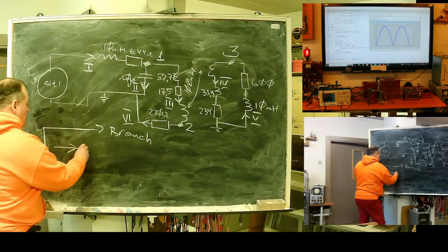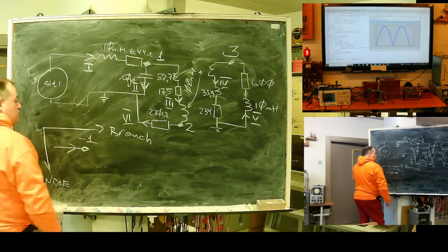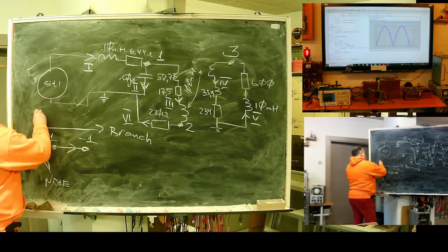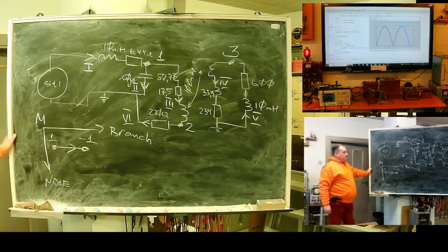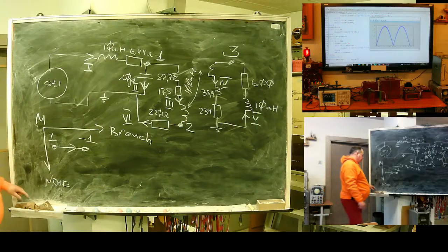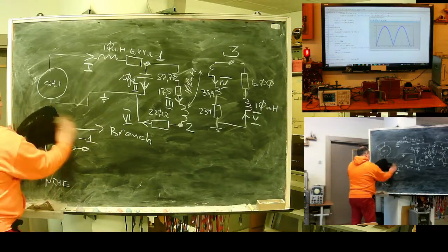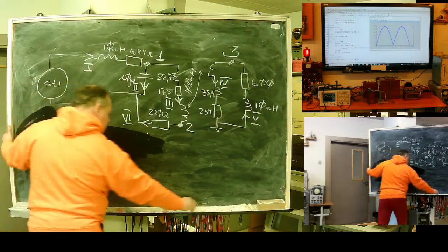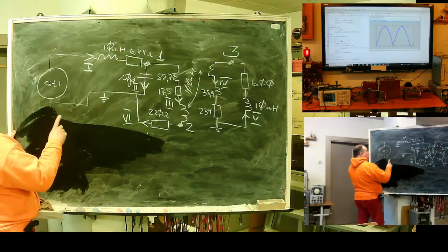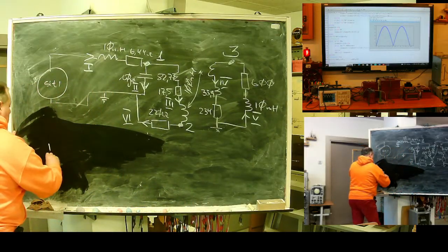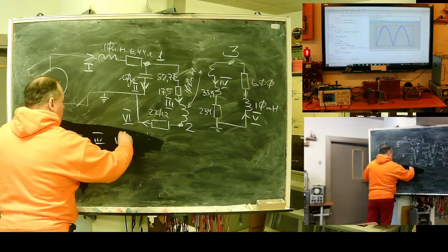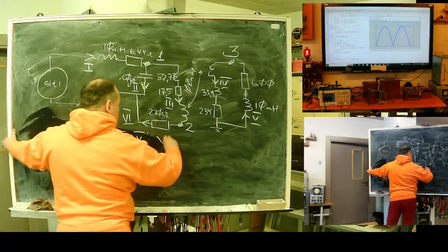If a branch inflows into a node, I write -1. If it goes from the node, I write 1. If there is no connection, I write 0. For my network, nodes 1, 2, 3, branches 1, 2, 3, 4, 5, 6.